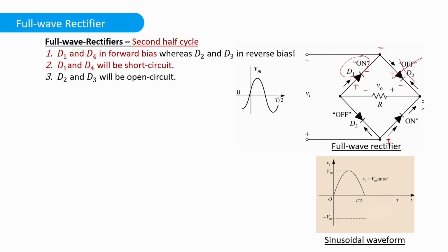Now coming to this point, this is plus. We can see this configuration is positive, this is negative, this is negative, this is positive. So this plus is connected with this plus, right? So this diode will be in forward bias condition and this D3 will be in reverse bias condition, which means it will not operate, right? So now we will have a flow of current in this direction, it will flow from here like this, then move towards this resistor, then goes here and goes outwards toward this negative sign.